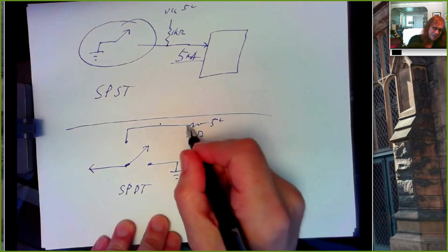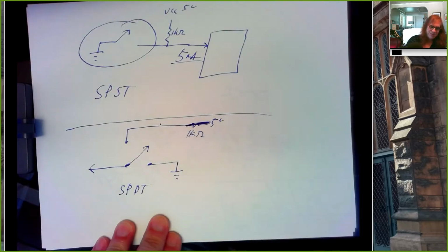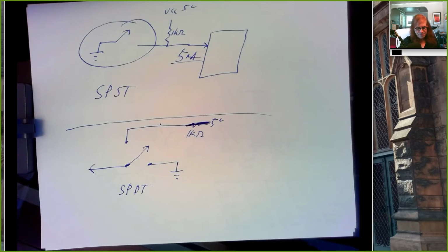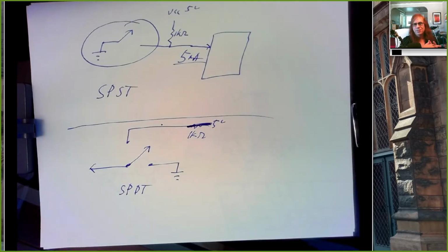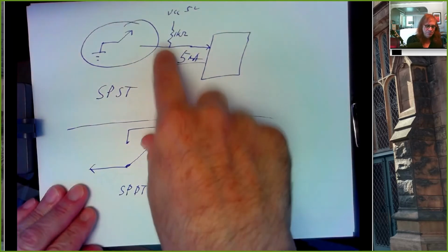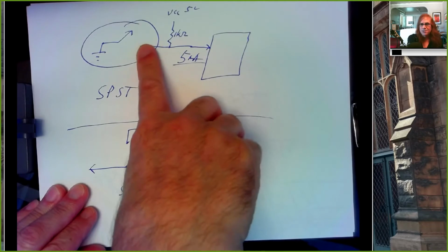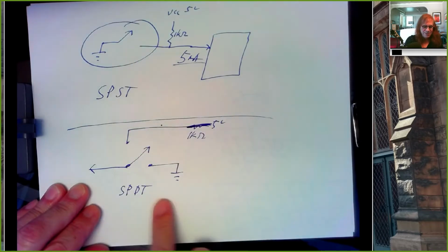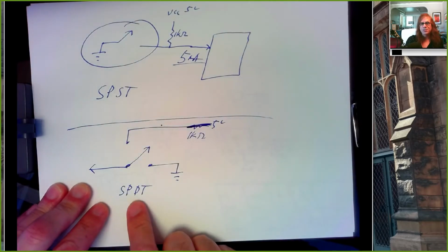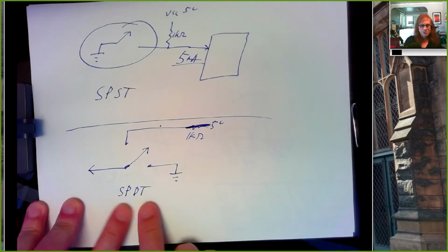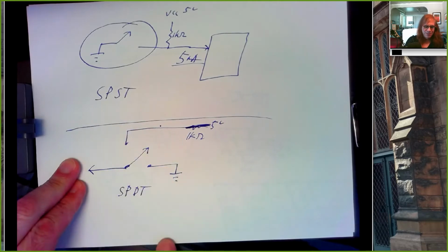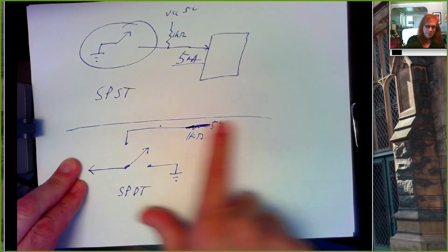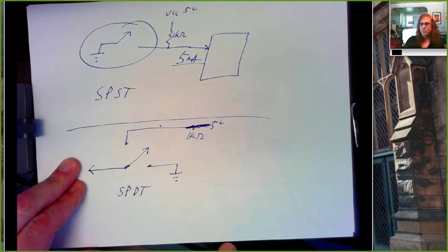And in Tinkercad, even if you forget that resistor, it still works. Some people in this lab, typically working on the delay circuit, weren't wiring up their switch like this, and their circuit wasn't working, and then they came across the red switches in Tinkercad. The red switches are single pole double throw. They're this fancier switch, and if you connect one end to ground and the other end to 5 volts, that makes it work.